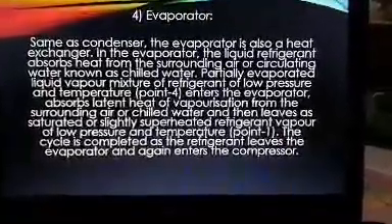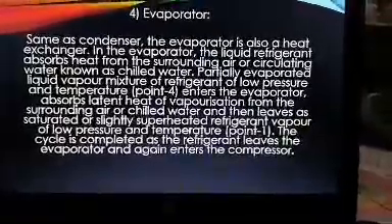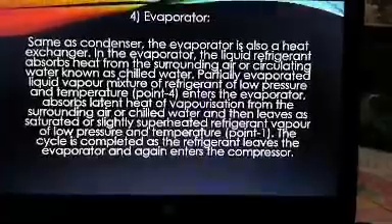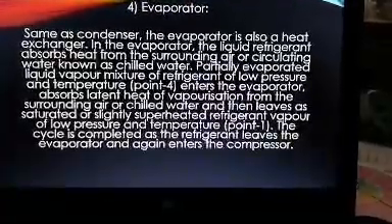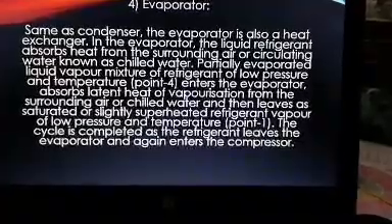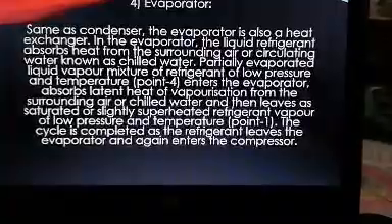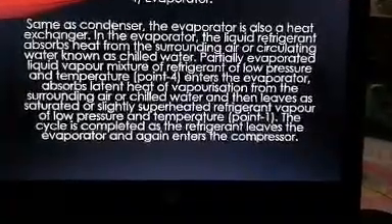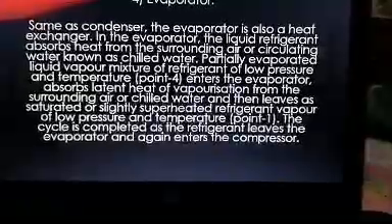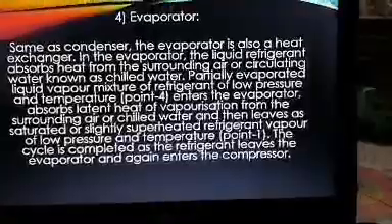The partially evaporated liquid vapor mixture of refrigerant of low pressure and temperature, point 4, enters the evaporator, absorbs latent heat of vaporization from the surrounding air or chill water and then leaves as saturated or slightly superheated refrigerant vapor of low pressure and temperature, point 1. The cycle is complete as the refrigerant leaves the evaporator and again enters the compressor.